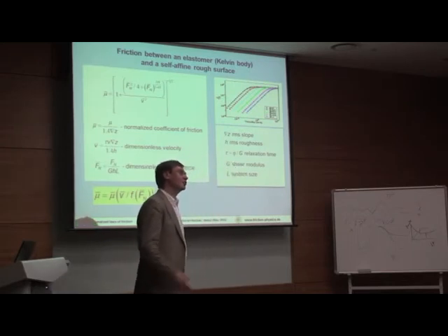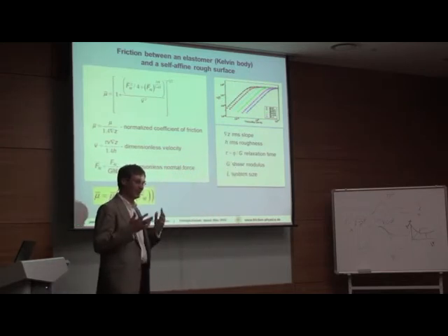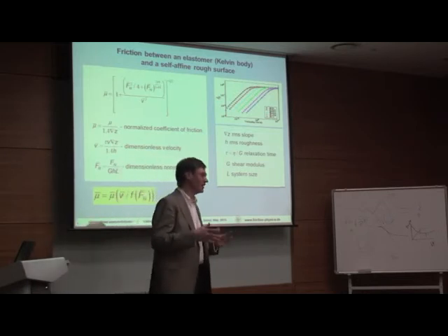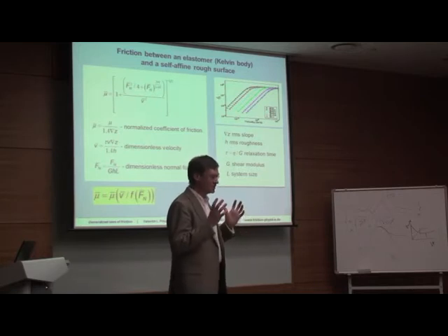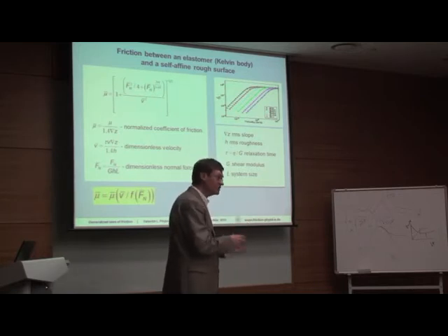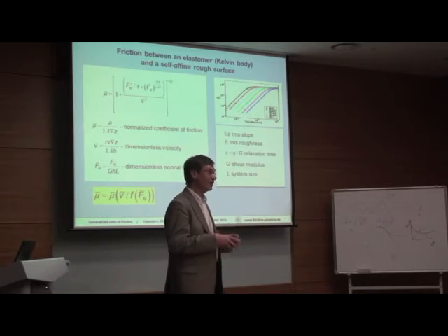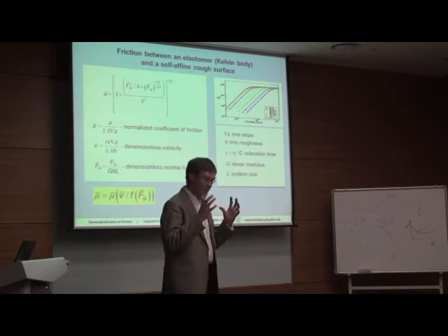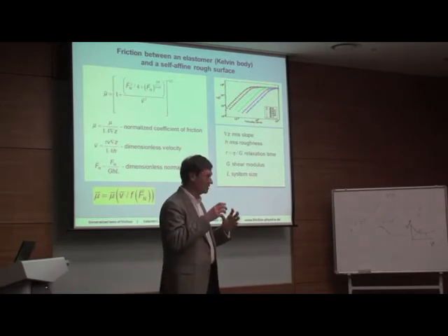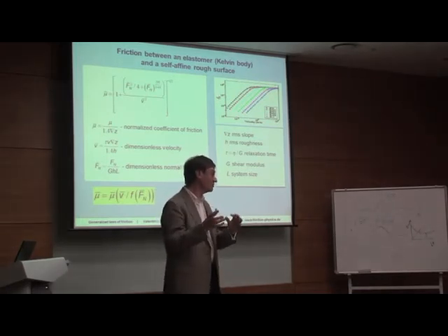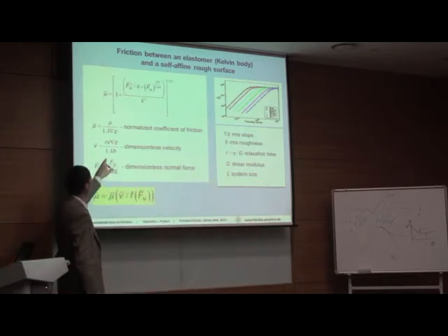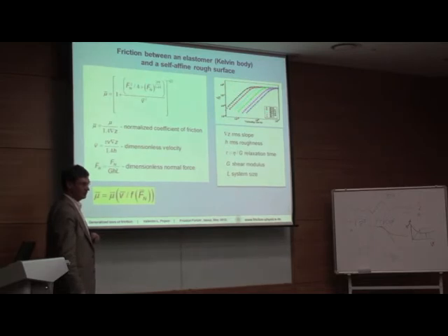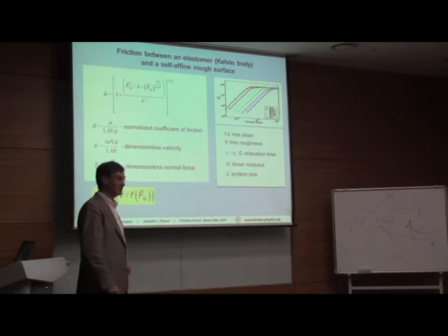Yeah, I consider this as an incompressible elastomer, so it is characterized either by the elastic or by the shear modulus. The elastic modulus is just 4 times the shear modulus. They are connected, so you can take another modulus, but then the coefficient will be different. It is only one modulus which characterizes the system completely.